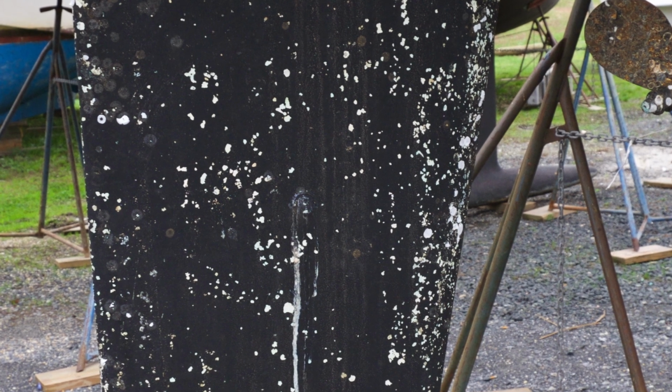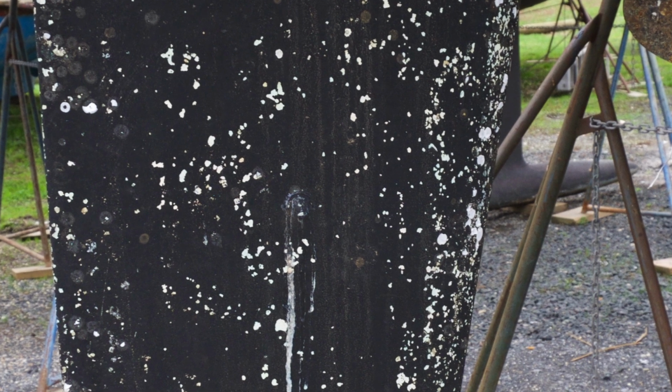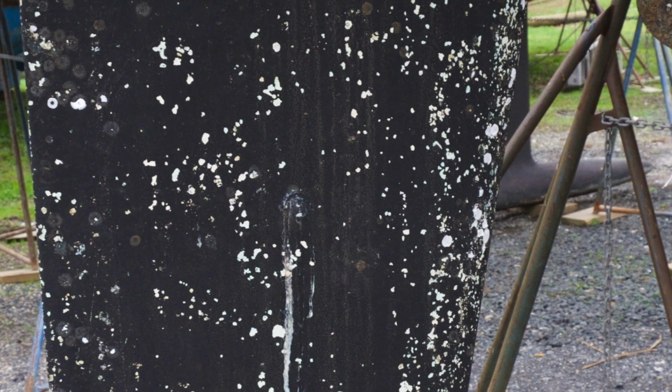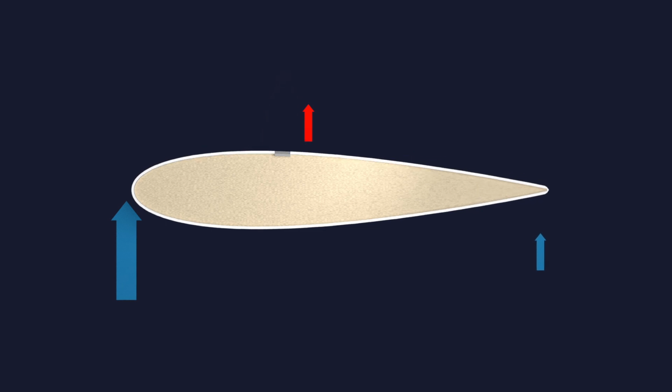Now, remember those holes open to pour the polyurethane? Those should have been glassed over. Instead, they were covered with putty. The putty bonded very firmly to the foam, but rather poorly to the thin edge of the skin. With such a configuration, it was easy for the skin to become detached from the putty, creating a path for water to enter between the skin and the foam.